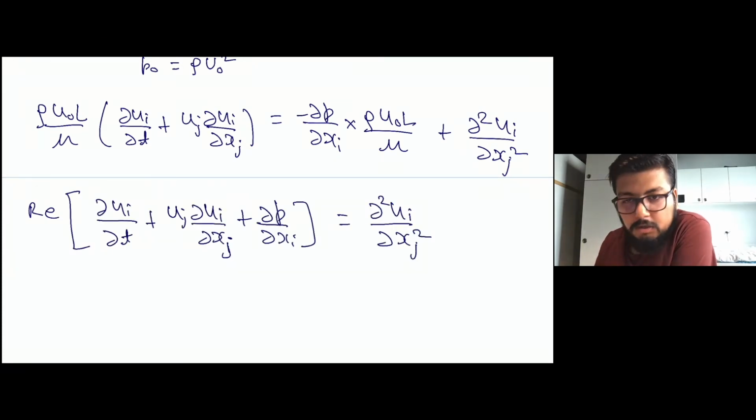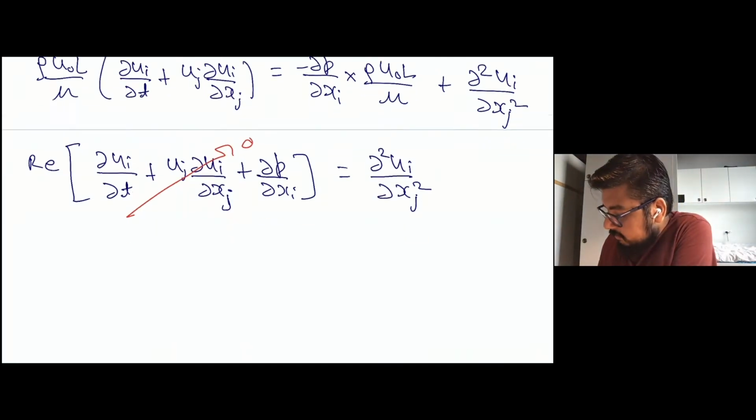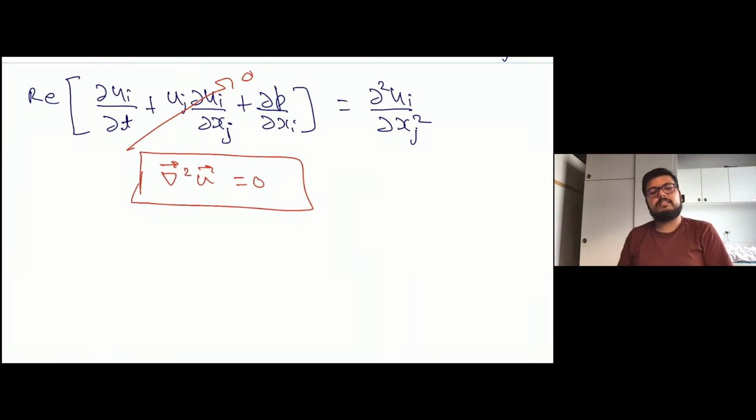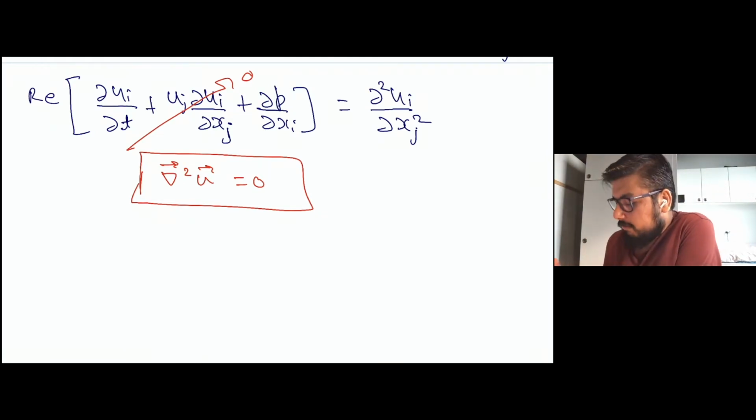Now if I take the assumption that the Reynolds number is very small, then the entire left hand side of this equation vanishes, and then I'm simply left with an equation which says that the Laplace of u is 0. Now this makes the flow really boring because we have no driving force in the system. So the flow is usually driven by the pressure gradient, and as we see that the pressure gradient has a factor of Reynolds multiplied to it, it goes to 0 if we assume that the Reynolds number goes to 0. And this is of course not how we will describe the Stokes flow.